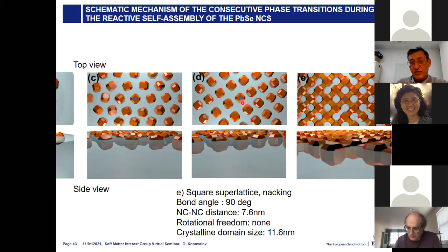It is just a kind of soft shell around them. And this oleic acid dissolves slowly in the ethylene glycol, and due to this very slow process of dissolving, it is removed one by one, and this gives time for nanoparticles to make a well-oriented arrangement between themselves. Afterwards, when all the oleic acid goes away, they can go close, face to face, stitch, and then afterwards create this necking process.